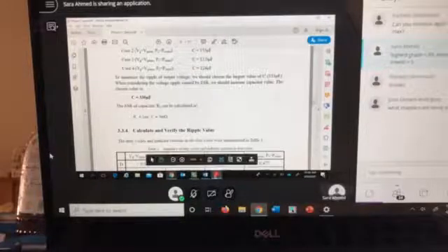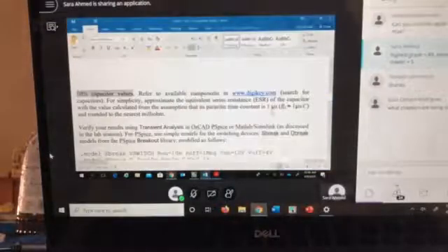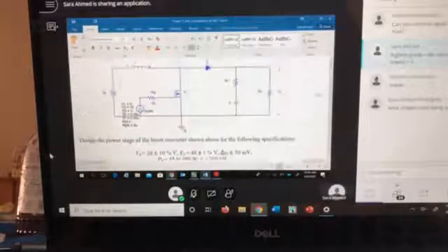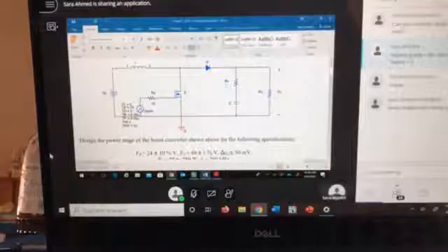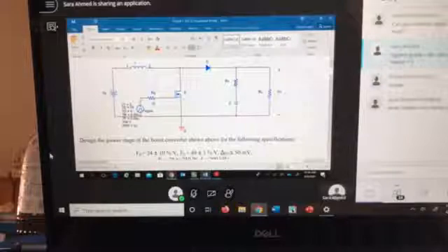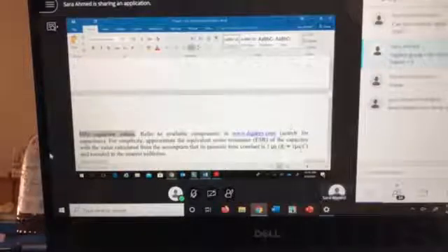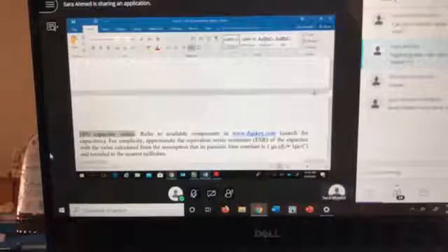R of C, if you remember, is given to you as 1 microsecond over C. So that's how you find its value. And when we talked about the project, I told you not to consider it when you're doing the equations so that it doesn't complicate them. That's what we did. We didn't consider it except after we found the capacitor, using this equation that was given to us, we calculated our R of C value, and then we're going to use it in our simulation.